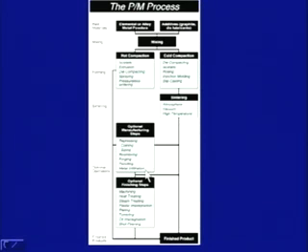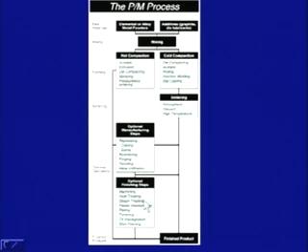Or there are other optional finishing operations. While discussing the basic manufacturing processes, I told you why finishing processes are required to get a very good surface finish. That surface finish will come if we subject our product to these finishing operations. So what finishing operations can be done to powder metallurgy parts? These finishing operations are machining, heat treating, steam treating, plastic impregnation, plating, tumbling, oil impregnation, and shot peening.